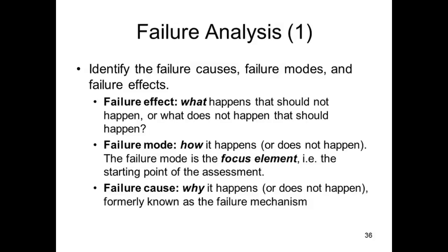From there, we go to the failure effect. Well, we don't know what the torque is, so we effectively haven't measured a vital process characteristic. And then we also look for the failure cause. Well, why might the worker forget to check the torque, which is the failure mechanism?